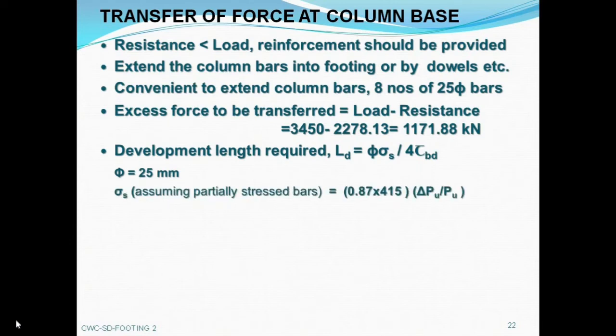Sigma s is the stress in bar at the section considered at design load, and we are considering partially stressed bars here. So it will be 0.87 Fy into delta Pu by Pu, where delta Pu is the excess force to be transferred, that is 1171, and Pu is the factored axial load.